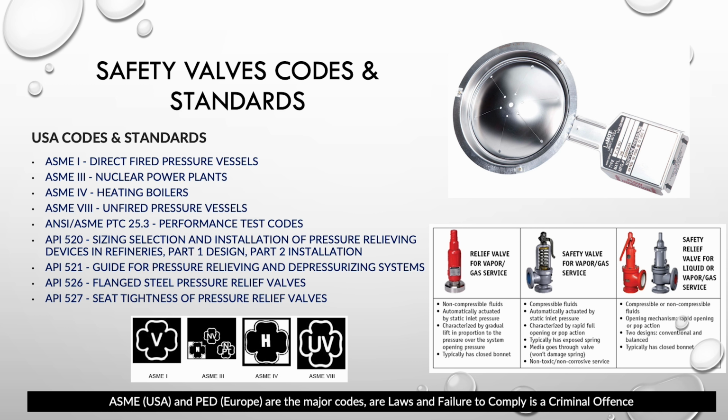So just because they physically follow the same principles of how control valves operate, they were not intended to be doing that. But again, to back up to our discussions, you are going to find so many codes and standards related to that. It's going to be like API 520, 521, 526, and 527. This is going to go through all the details of how a pressure relief valve is sized.